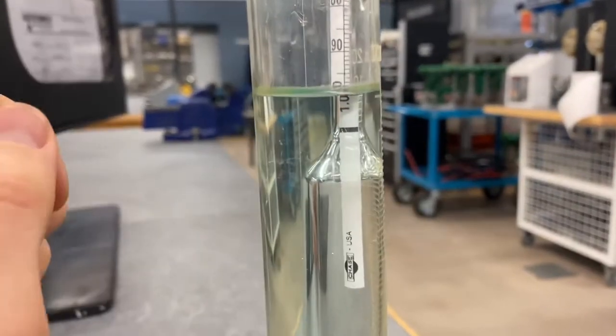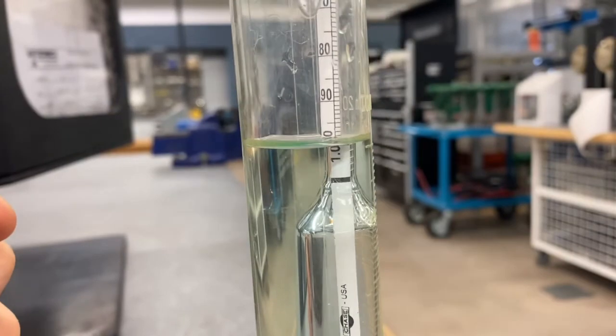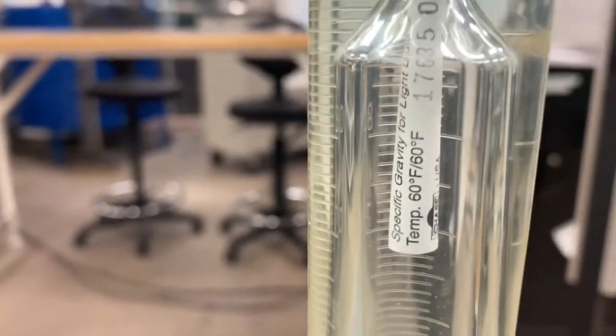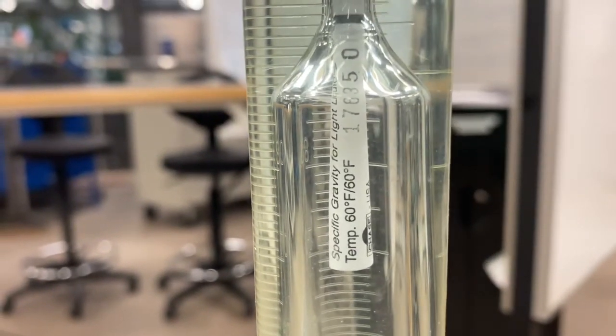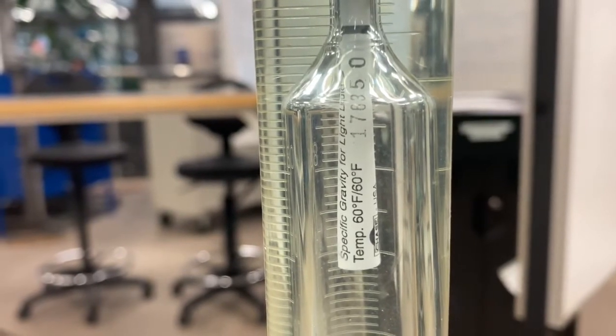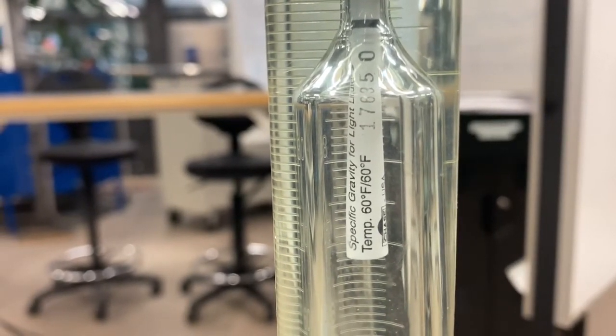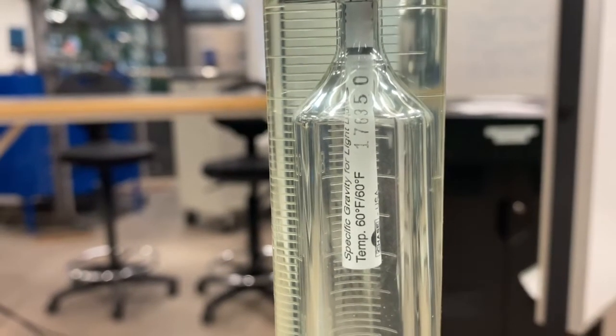All right, so I've taken a sample of the water that we were using to run through our meter here, and I've put this hydrometer into it. It will figure out our specific gravity. I believe if you look, yes, right over here, the scale is in specific gravity, and it was used at a temperature of 60 degrees Fahrenheit. So we're a little bit warmer than that. 60 degrees is about 15 degrees C. We're about 20 or 21 degrees C at room temperature, so this fluid's probably around 20 degrees C.